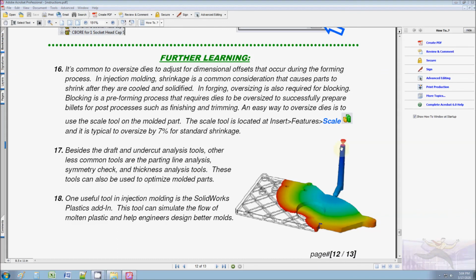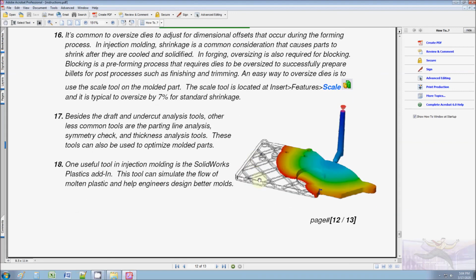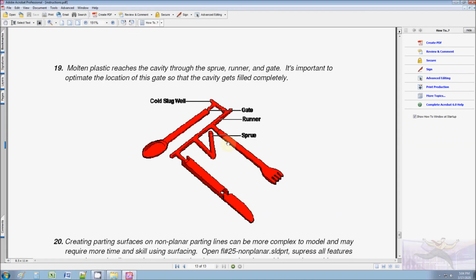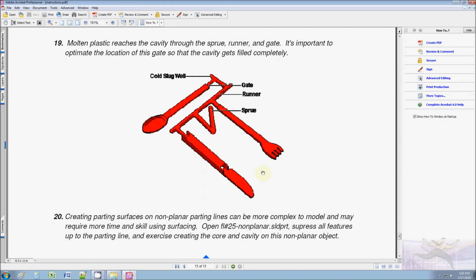Also, another thing you've got to realize is where you inject the fluid, where you inject the flow. You don't want to get a short shot on the ends of this cavity, so you've got to make sure that the fluid is well distributed throughout your model. Okay? Because again, you really want to mold everything in one place, in one shot. This way, everything is uniform. So you really got to think about where you are injecting. Is this a critical area of your model? Is it okay if you get a little residual feature that comes out of this when this is assembled?